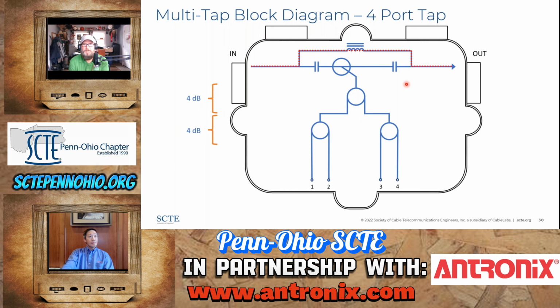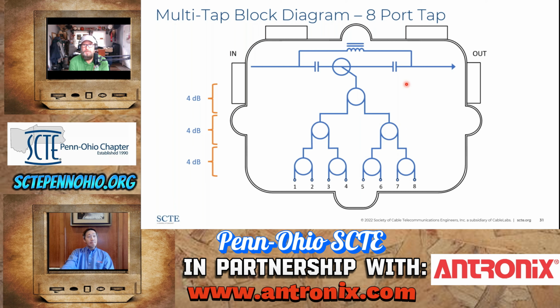Awesome. So these are combination devices. They have a directional coupler and a splitter or a series of splitters. And that directional coupler is what determines the insertion loss from the in to the out. And then the sum of the loss through the directional coupler and the series of splitters is what determines the loss from the in to the tap port.